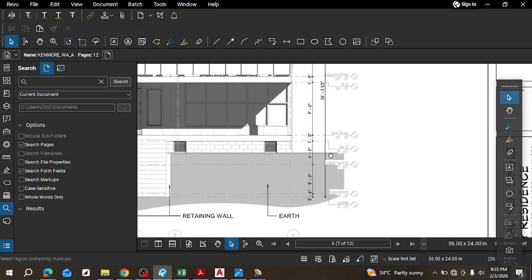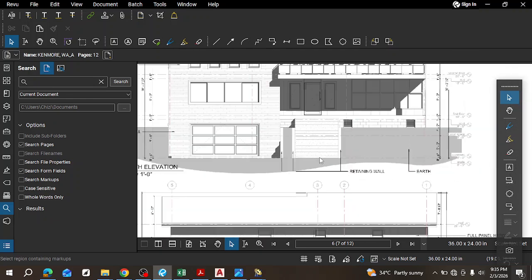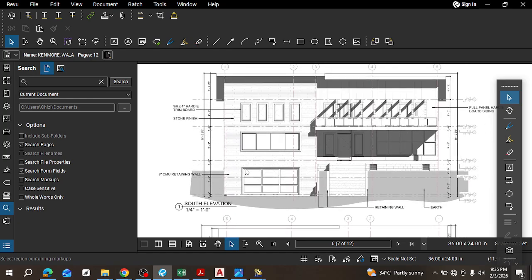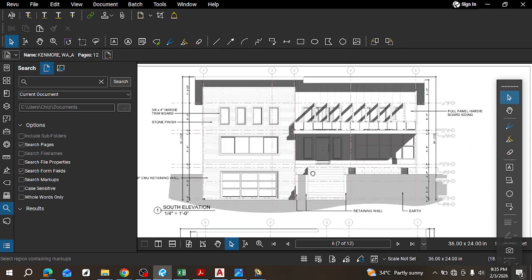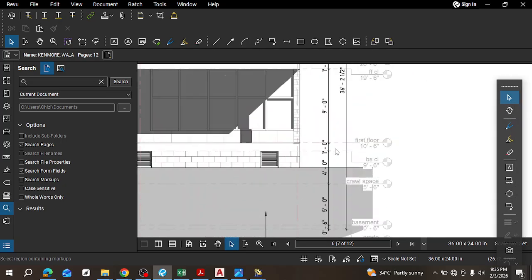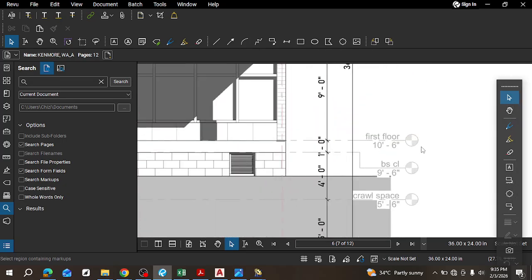Okay, now back at this architectural file. So we see that according to the elevation, this is the basement, first or second floor. And obviously our sprinkler is to be on the ceiling. So this will be the ceiling level of the first floor. First floor ends at 10 feet 6 inches. So put it at 10 feet.